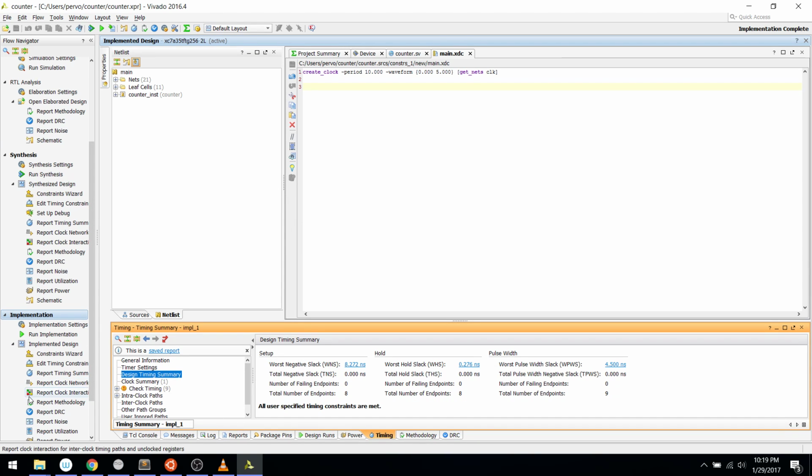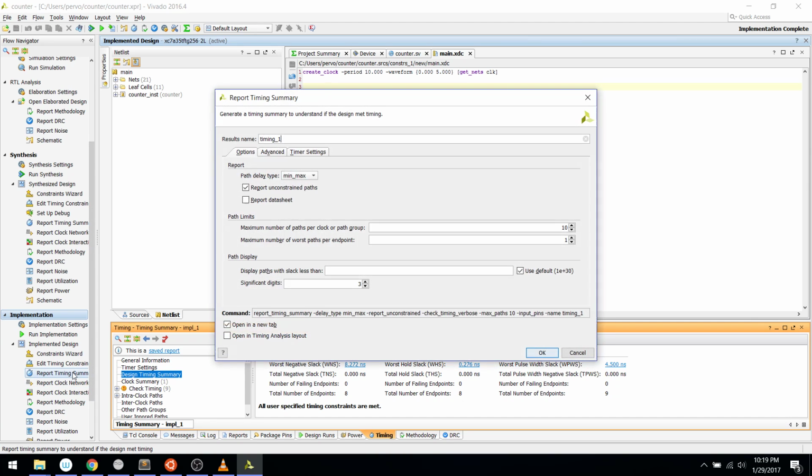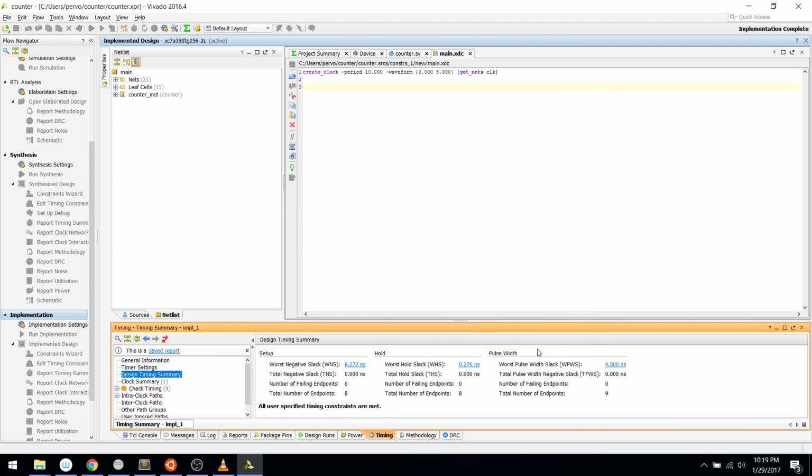All right, this looks like it actually is correct now. It has the timing slack and everything. But let's just make sure. Right, so this actually works. So let me explain this timing view, and some of these warnings should be gone now. Yep, the no clock warning is gone.